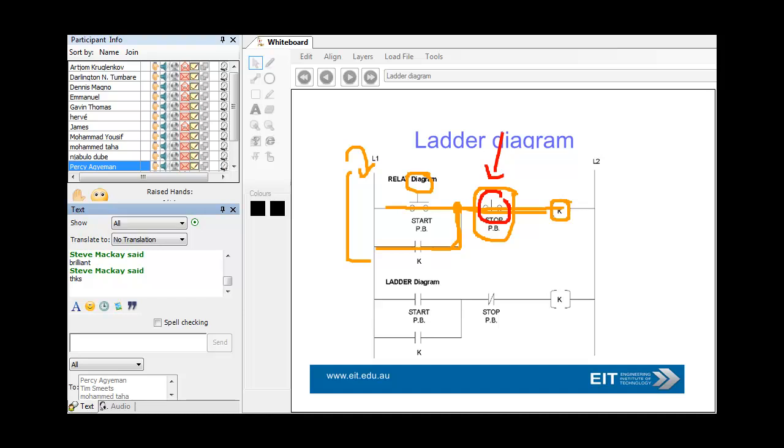So, emergency stop button, I've got my hand in the conveyor belt, I pull the pull wire, it trips it out, whatever the programmer has done. So obviously very important that this is fail-safe, and it's external to the PLC as well. So that's not an issue.